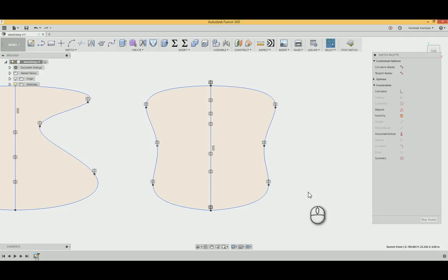No, you click on one thing, the thing you want to be symmetrical, and then the mirror line. Okay, because it's not letting me click more than one thing when I try to do that. Oh, you know what? It has a constraint of some sort. Right. When something doesn't behave the way you expect it to, it probably has some kind of constraint already. You inadvertently, yeah. So you hit the point, you hit the second point. Right, and then you hit the mirror line. And then you hit the mirror line. Okay, now they're symmetrical. Got it.